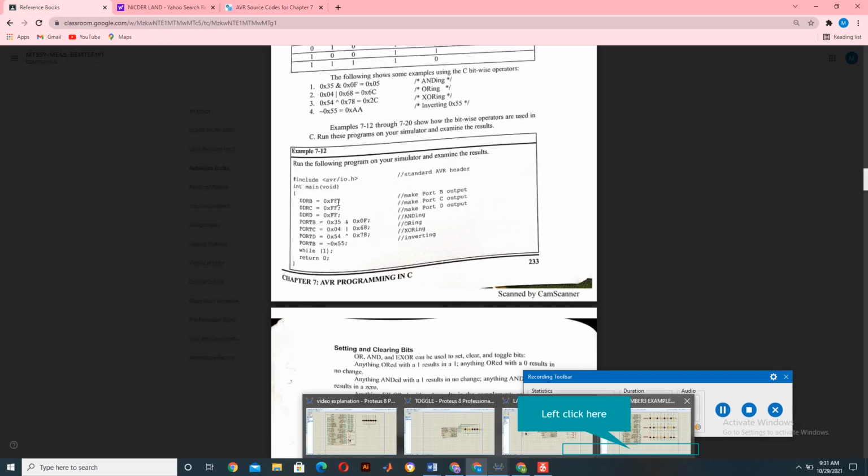What happens first, it has taken the direction that all the ports A, B, C, D are all zero. This is an Arduino Uno code, so that's why they had not taken A; instead of A they have taken D. But as I was using Mega, you can also take port D. But I have used port A to get a better simulation result, although it would remain unchanged. Still, for better use and understanding, I've used A instead of D.